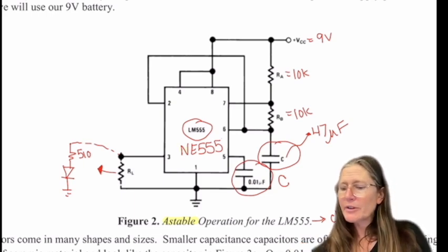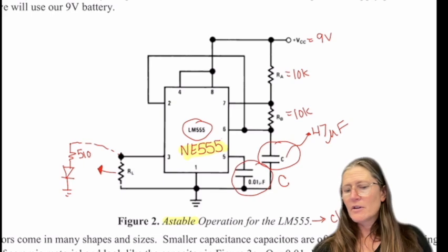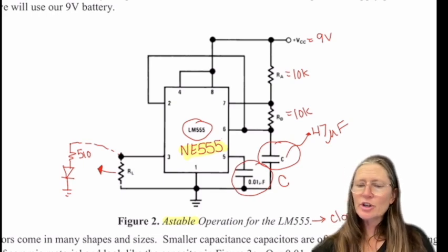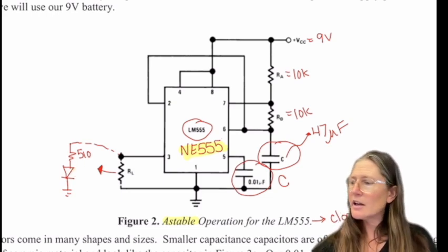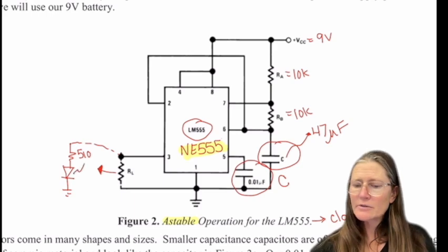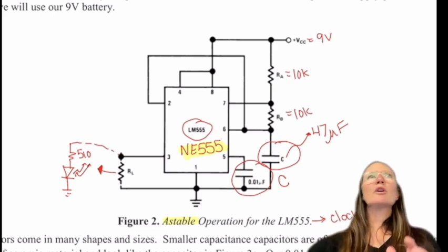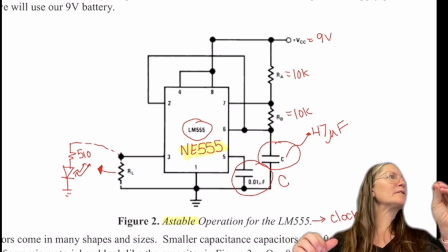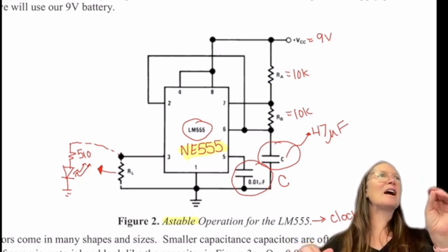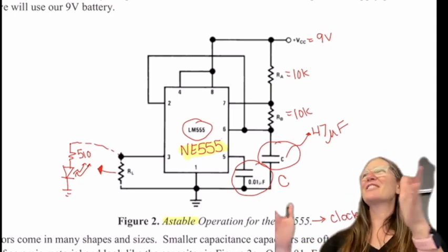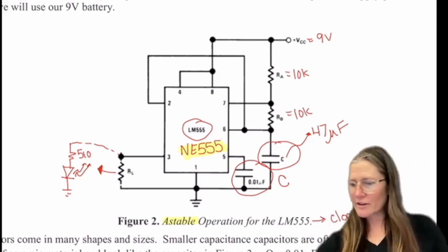The chip is NE555, and then the elements you're going to look for are R for resistor, LED for the light, and C for capacitor. If you don't have LTspice on your own computer, please meet your neighbor that might have it and work together to create this.